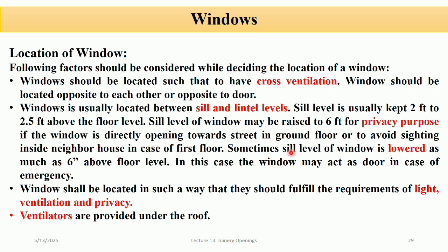Lower sill level in special cases. So sometimes the sill level of window is reduced to as low as 6 inches above the floor level. So such window may serve as an emergency exit, acting like a small door in case of fire or other emergencies.